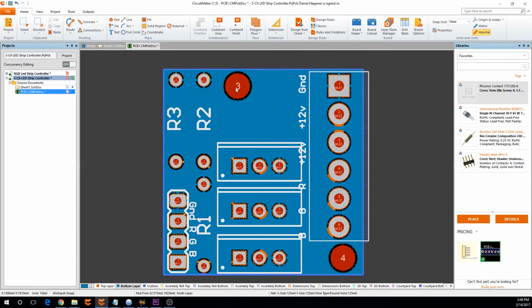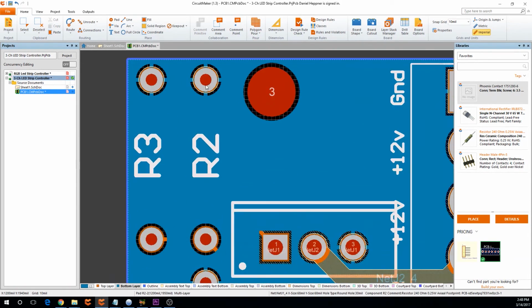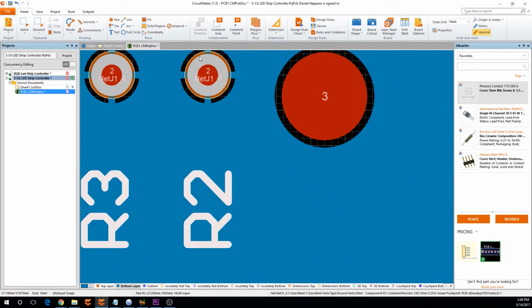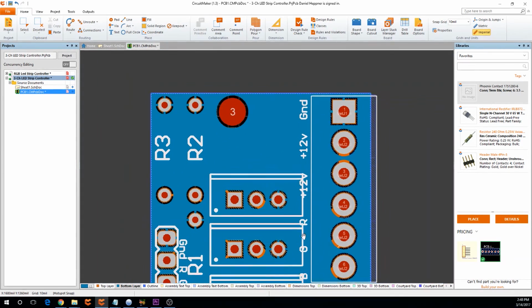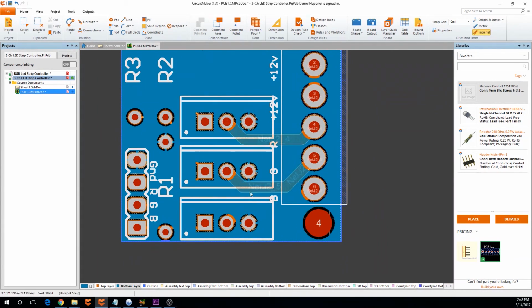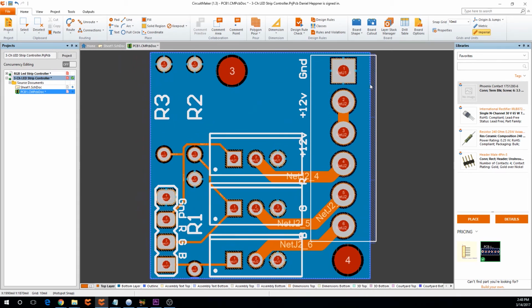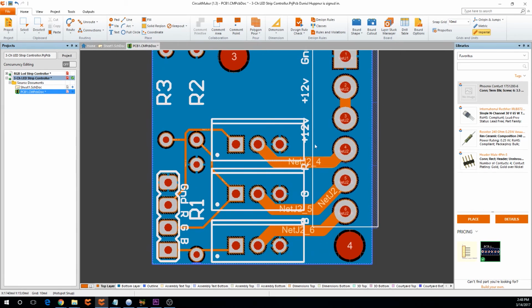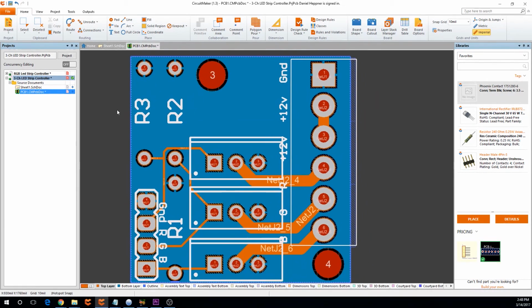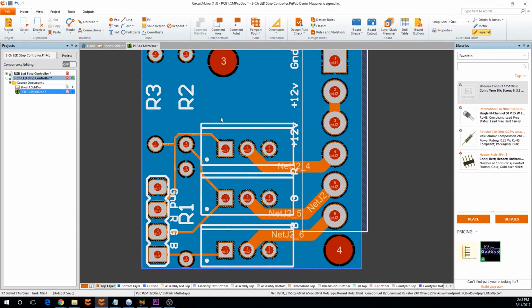And you can see it filled everything in, and if I zoom in on this, you can see that it connected the pins of components that are supposed to be connected to ground. And if I go back and put the top layer on top, you can see that's still there. So now all the grounds are connected together through this plane that will be able to carry a lot of current. And that's good, since these grounds of these transistors are going to be feeding current back to this ground, and everything's just connected together. Low resistance. This is ideal.